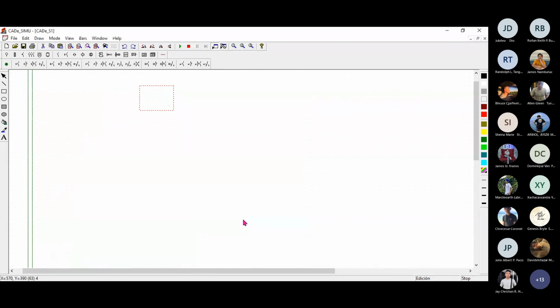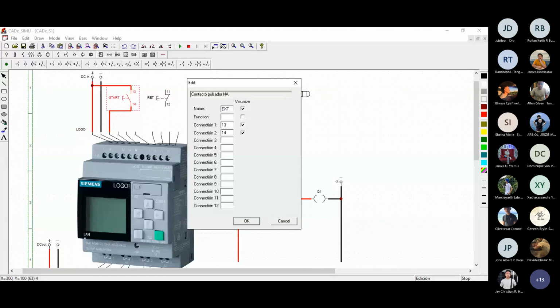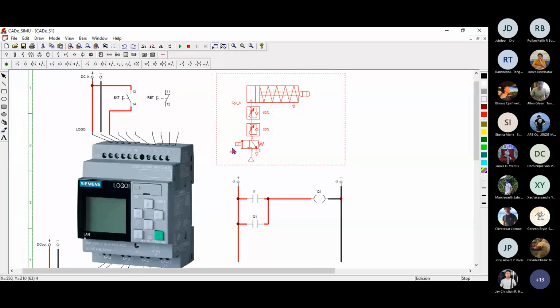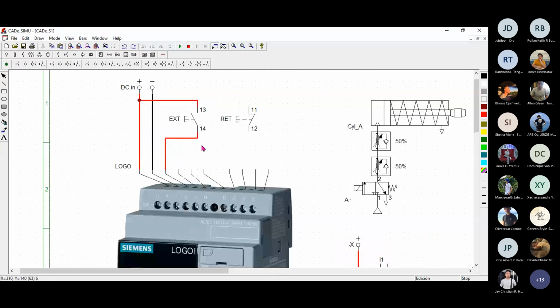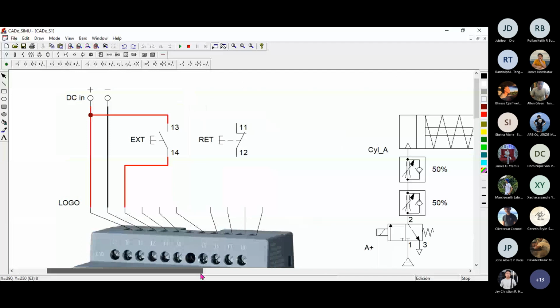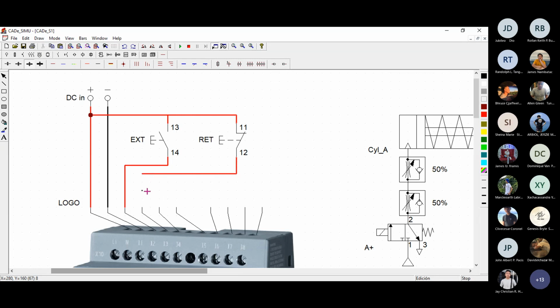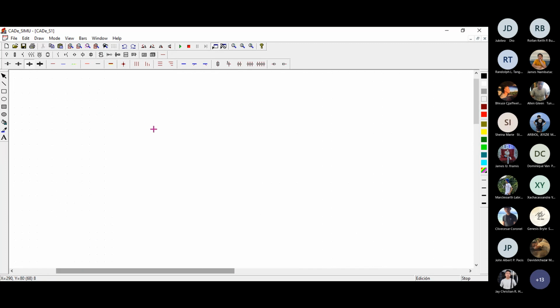How do we connect the input? Again, as I mentioned a while ago, one end is connected to the positive wire, and then the other end to the assigned input, shall we say I2. Although you can choose your own, like let's say I3, I4, I5, I8. It depends, so long as you remember the address of that particular switch.